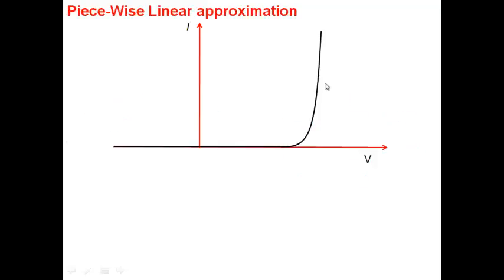Well, so here is the diode characteristics, and I'm approximating it not by a vertical line. We've already preempted this particular discussion in our homework assignment. Remember, we approximated by a straight line rather than a vertical line, a line with a slope here. So here is the diode characteristics. There are different ways of approximating. This approximation is with a V gamma and a slope here.